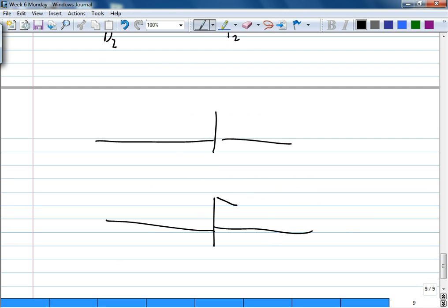A small guide vane or nozzle. So it's like a cylindrical trumpet, to guide the flow so that you don't get so much losses. It works a little bit, it's better, but it's not that fantastic. And then this is your point 2, this is your point 1. It costs more than the orifice plate, but less than the Venturi tube, and its performance is also better than the orifice plate, but not as good as the Venturi tube. So it's an in-between kind of solution, with some guide vanes.